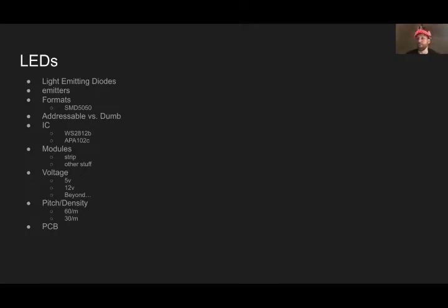Do you want the printed circuit board to blend into the background? Are they going to be adhered to some painted structure? Would you rather have a white background, which has the capacity to reflect some of the light and make it a little bit brighter? Or would you rather have a black background, which is easier to conceal and makes the LEDs look more streamlined, or difficult to recognize as electronics? There are advantages to both.